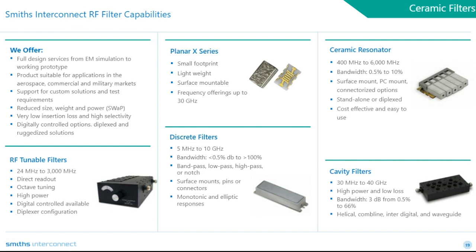What type of power can ceramic filters handle? Thank you, Katie. I'll take that question. We've recently tested our ceramic filters up to 16-watt continuous, and that was this year. So it depends on a few different factors, but they can handle some pretty good power. And like I said, we were successful up to 16 watts continuous.